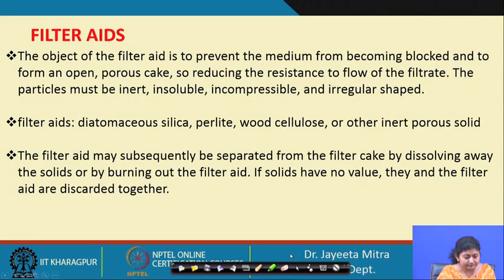And what are filter aids? The object of the filter aid is to prevent the medium from becoming blocked and to form an open porous cake, so reducing the resistance to flow of the filtrate, okay? Because if the resistance is increasing, flow rate will decrease. That is why the particles must be inert, insoluble, incompressible, and of regular shape.